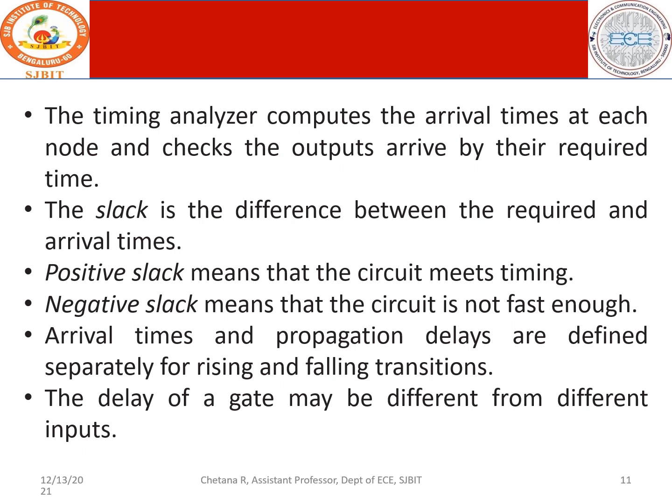So 1 minus 0.8 is positive slack, whereas 1 minus 1.2 is negative slack. Therefore it is not meeting; instead of 1 second it is taking 1.2 seconds. So that is negative slack. So the circuit design is not good enough or fast enough. We need to improve that.